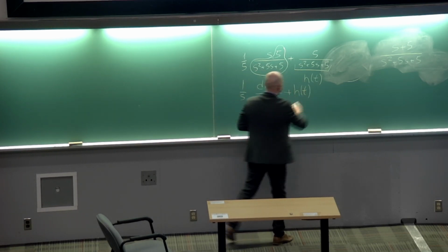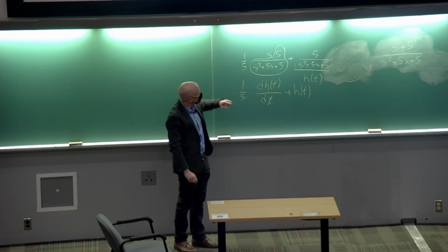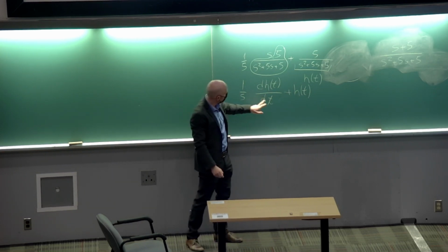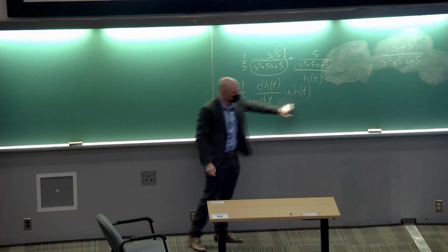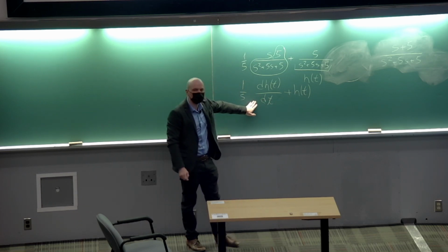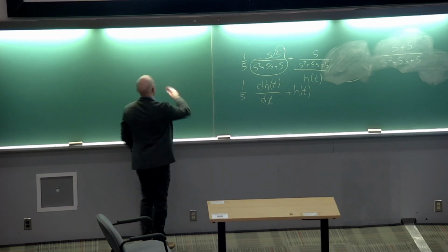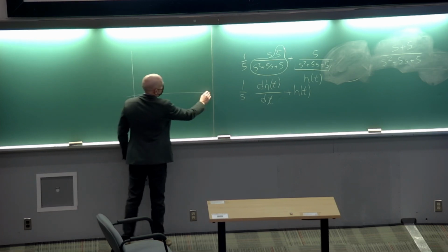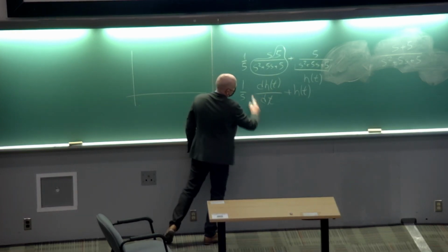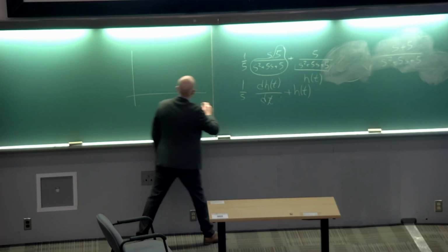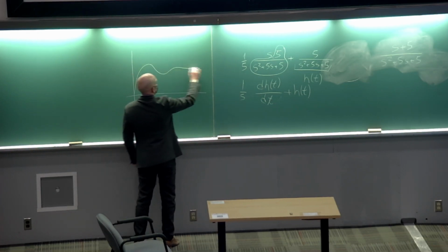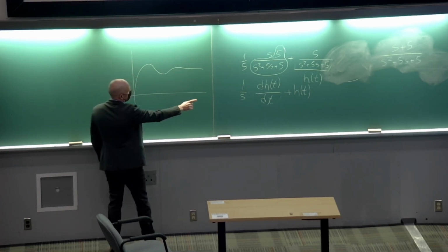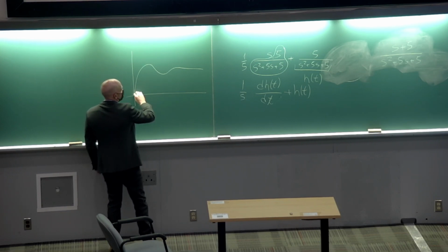So what are we doing here? The time response now changed a bit because to the time response, the original function, we are adding its own derivative. So as the 0 is making all the function, we are adding something to the function whenever the derivative is non-zero. So if h of t was like that, we are now adding to it dh of t dt.